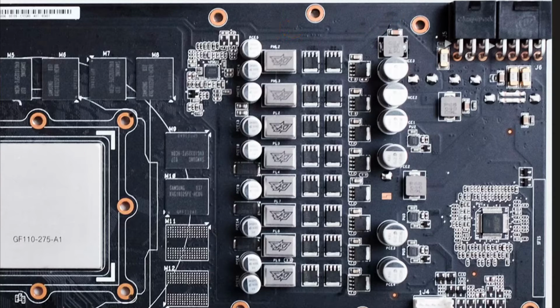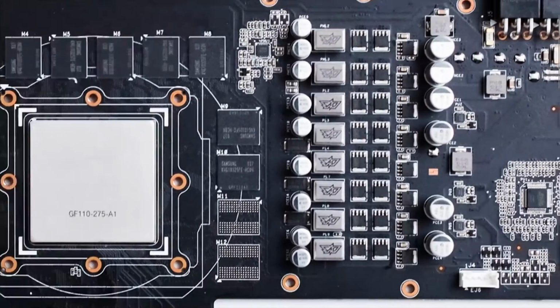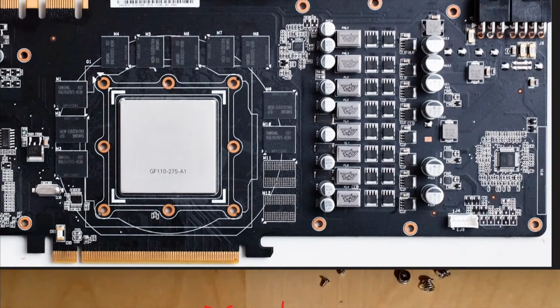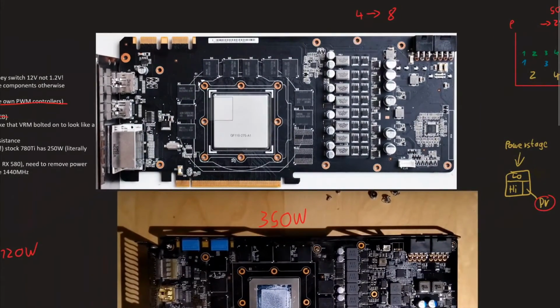So yeah, when you look up current ratings for MOSFETs in datasheets, or basically for everything, you have to also look at which voltage the current is rated.